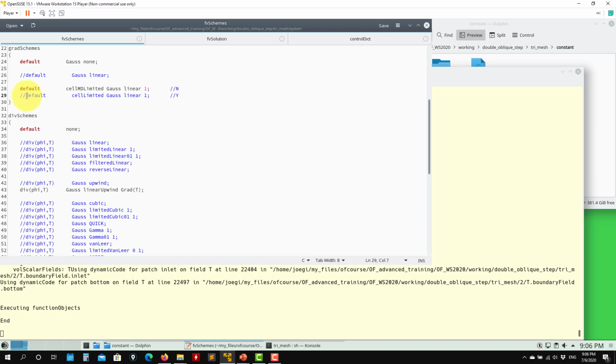So usually when you add this limiter, that probably is the most diffusive one, it will limit all the gradients in all directions. Okay, so if you have one phase that is becoming unbounded, it will limit all other phases in the same way. Okay, so it will add some diffusion. This is something locally. In this case, this is kind of selective. So only the direction that is becoming unbounded. So it's more accurate, but it might be a little bit more oscillatory. So that's why also I don't like to use that one. I prefer to use this one.